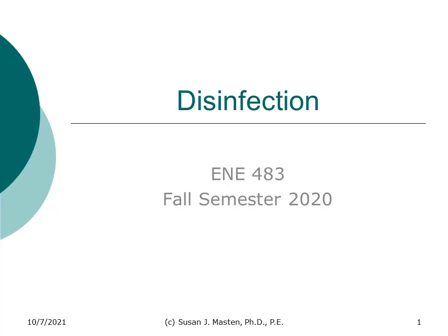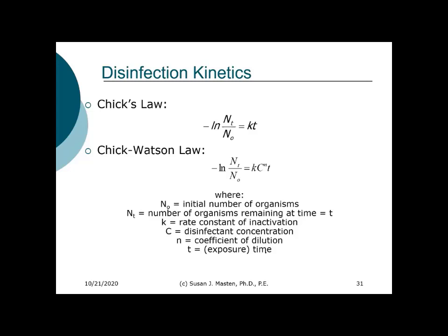In this unit, we will look at the kinetics of disinfection. We can model disinfection kinetics with a first-order reaction. So this is a simple first-order reaction where we're modeling the concentration or the number of organisms at any time as a function of a constant and time.